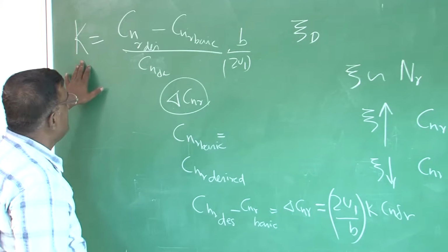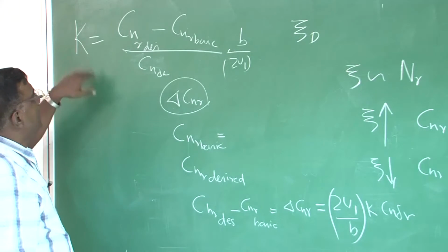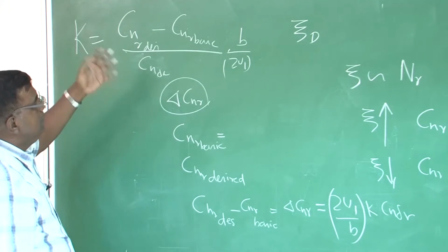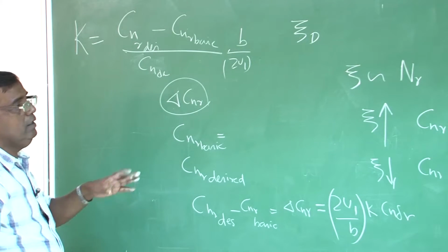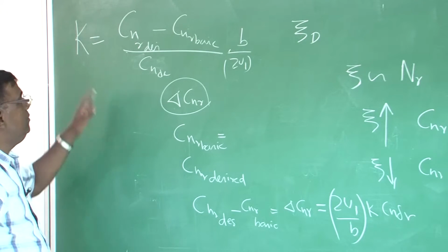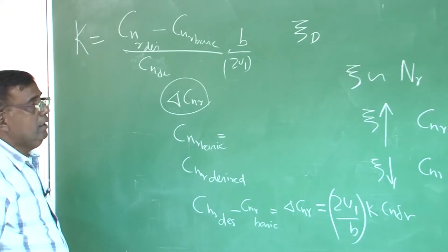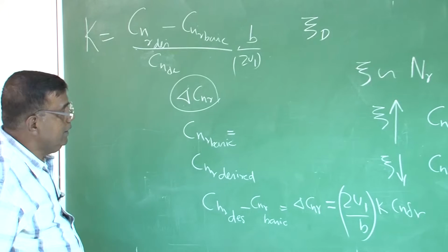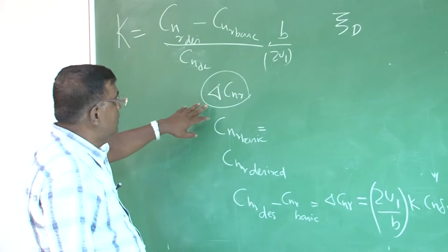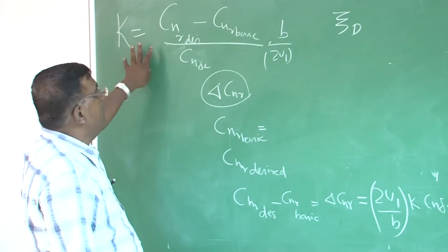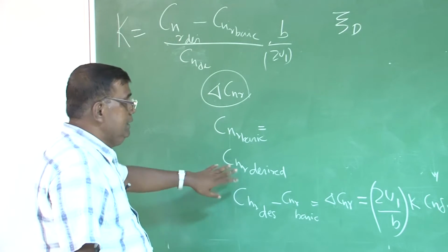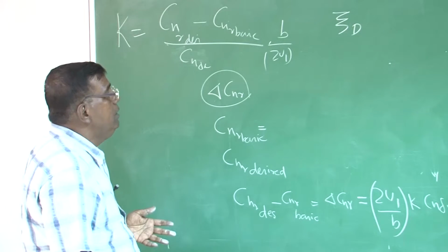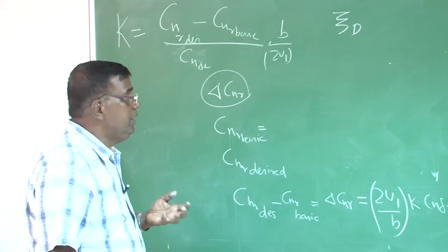This is K. Right? And again, as you know, I have to fit this back to the dynamic stability exact equation and see how the roots are changing, because it will have an effect in other derivatives as well. See, I always say that this is the value of K which will take care of the new value of CNR required, so that you have a correct damping ratio.